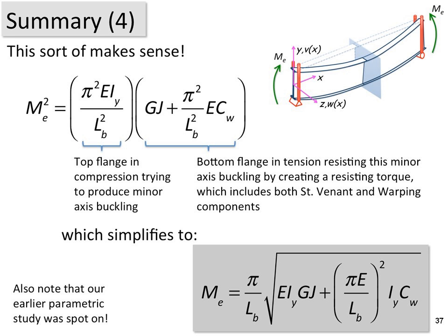Yes, it is. If the person there has the 2010 specification, I believe if they look on the next page, they'll see a user note that provides this equation, and the user note effectively says that big ugly equation on the previous page, which is trying to also give you elastic LTB moment for channels as well, reduces to the equation I'm showing for wide flange sections. So yeah, they're the same thing. And again, that's even one of my assignments for the students, to give them the really ugly one, and then tell them, now, wasn't it worth just turning the page over and seeing that user note that tells you for wide flange shapes, you can just use this more simple equation. But they'll give the same results.